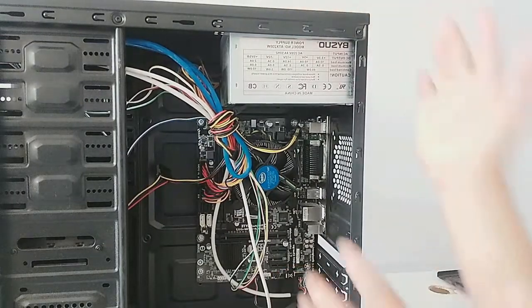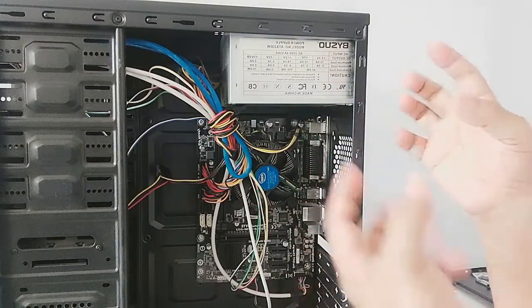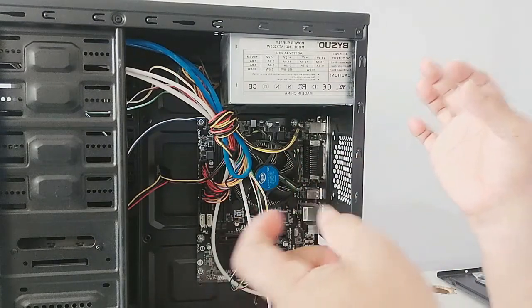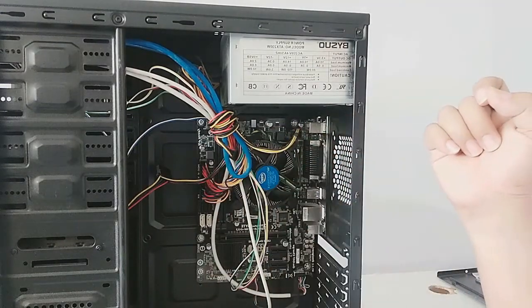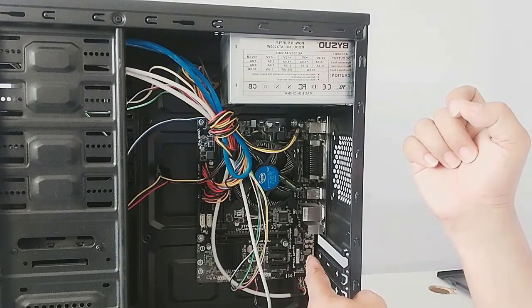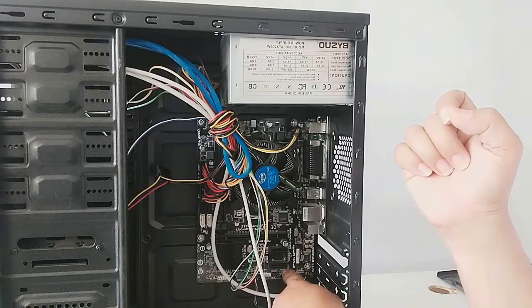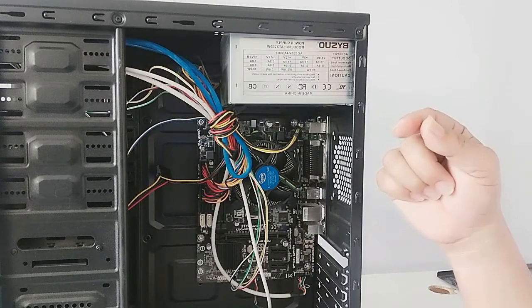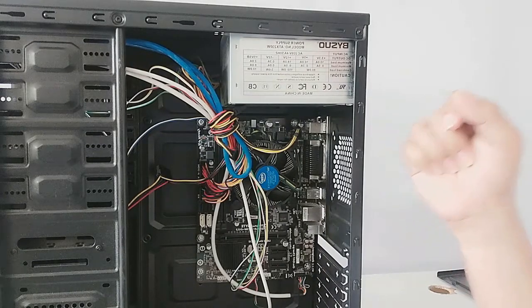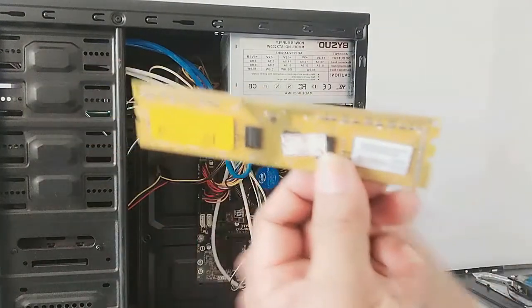Just always remember that the orientation should not be inverted. In case the pin doesn't match the slot that you are trying to insert, that is an indication that it is not for the slot that you are trying to insert. Alright, so never apply force because the pins here are actually sensitive. They might be damaged in case you apply force to them. So you have to be very careful with that.